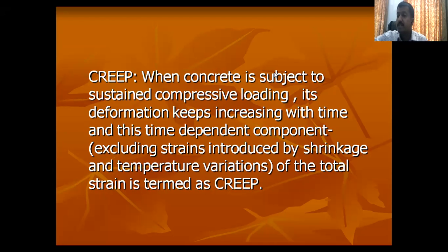You can do so, but it is impossible. Okay, next to impossible. But you can stretch out that particular reinforcement. I think in your universal testing machine, you have done that practical also, the tension test on the material. So you are going to stretch the steel reinforcement like a rubber. It is strong in tension. So reinforcement is being provided just to improve the tensile strength of your concrete.